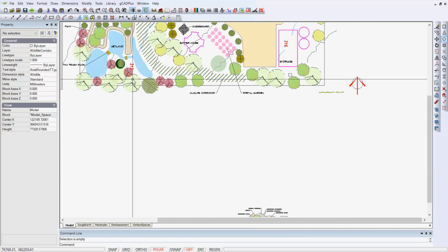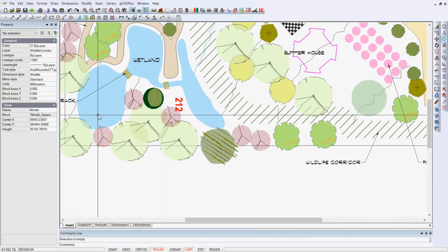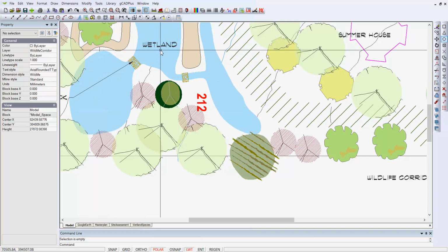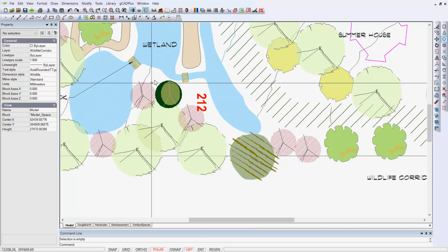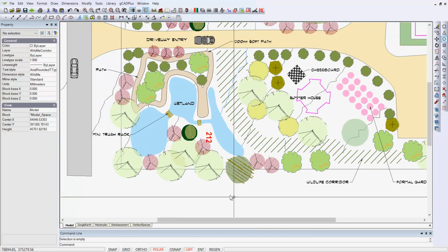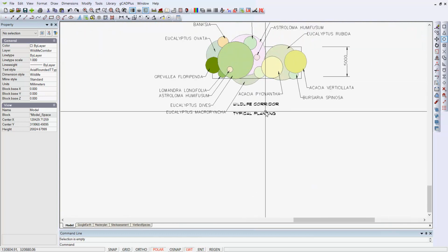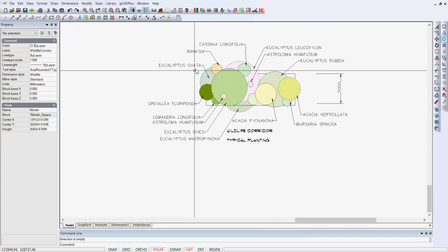If you wanted to do more on the detailed wetland design, we would probably include an island in here, but this design was done more as a concept one, so we'd increase the shoreline as much as possible, provide a haven in here maybe for birds to breed, and do some heavy planting around the shoreline, and I'd be inclined to detail it in much the same way as we've done here. There's a typical planting through that wildlife corridor.